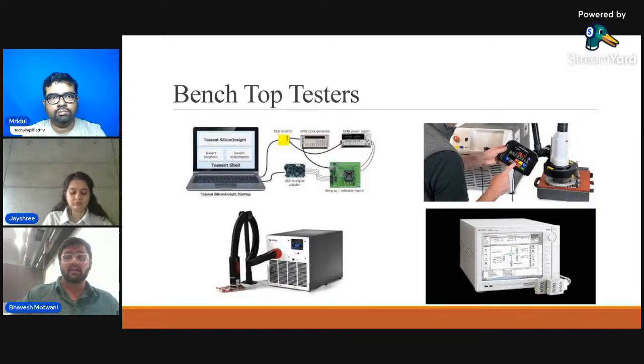After making a bunch of packages, just changing one parameter can bring a huge change. So testing is very important, and it should be done step by step. If I have done the die test, then do the inspection. If I have done the wire bond, do electrical testing and mechanical testing. After encapsulation, once I have packed the IC, I can do the mechanical testing. All these parameters are very important to check, and then we send the batch to the customers. So I think that was it.